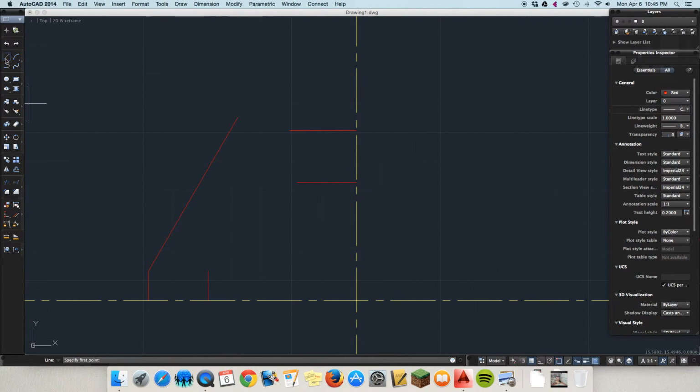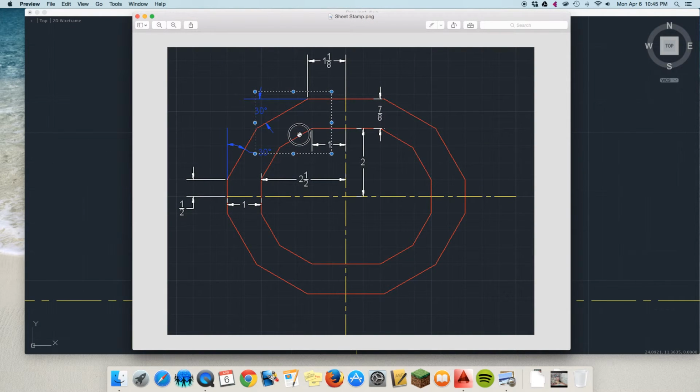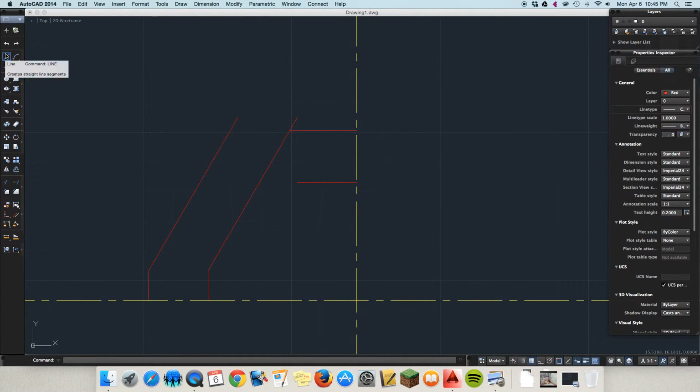We're going to do the same thing on this one. Okay, click here, type in 3, tab, and 60 is our angle again. Hit enter. Okay, now don't get confused, because this is coming way up here that we're done. If you look at the drawing, we have 2 more angled lines right here, these red ones. And the issue is this time 30 degrees is coming from here, but they're really measuring from a straight line. Okay, so a straight line is 180 degrees, so 180 minus 30 is 150.